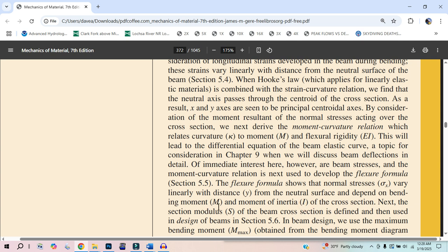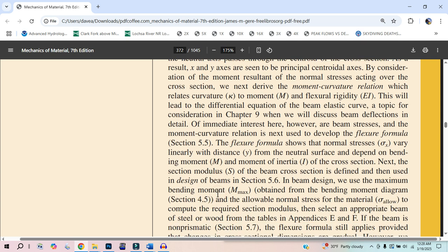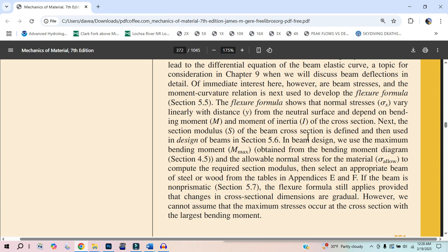And then the moment that's applied is the load that you can put on it. So if you rearrange this equation, without writing the equation down, sigma is equal to My over I. This is how I think of it: My divided by I. And this moment of inertia, this cross section, can become bigger if you make it a nice little I beam, and we're dividing by that.